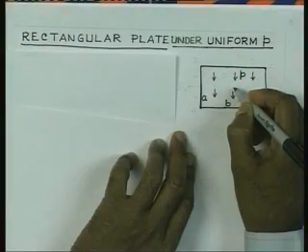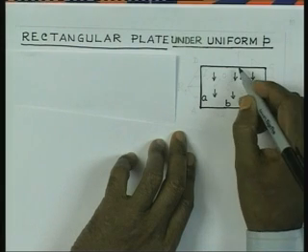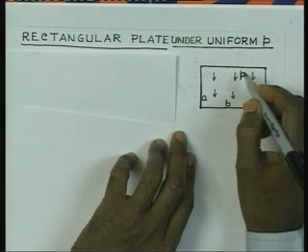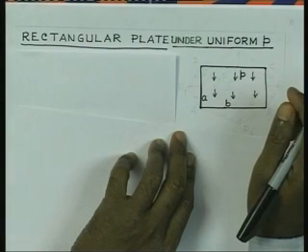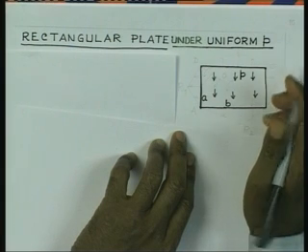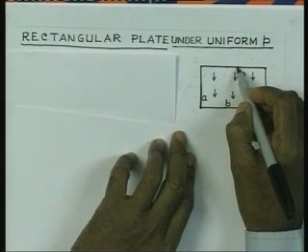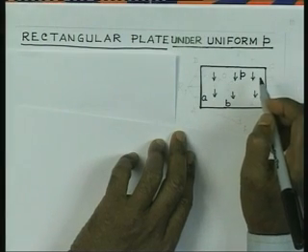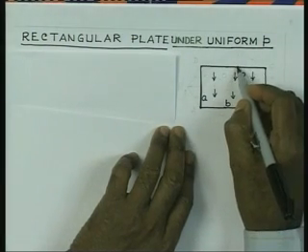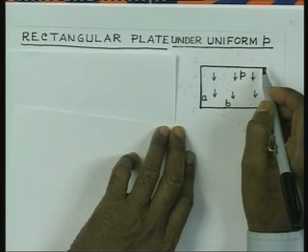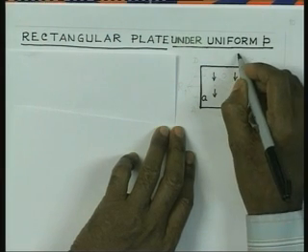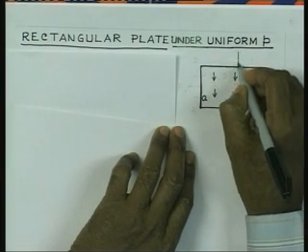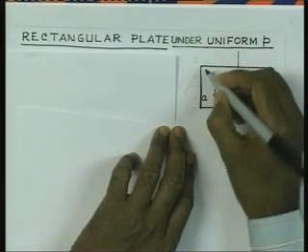Here the center of loading is exactly at the center of the plate, and these middle points of the sides are closest to the center of gravity, and therefore, what you find is that reaction is going to be non-uniform and it is going to vary along the boundary. If we just assume that the reaction forces at the boundary vary linearly, then we can consider that the reaction is going to be the maximum at the center of the side.